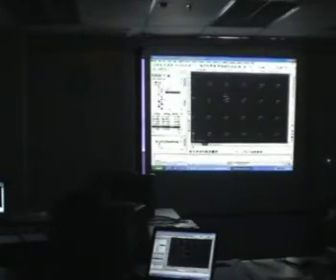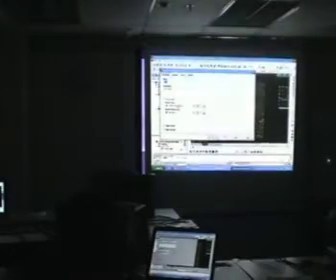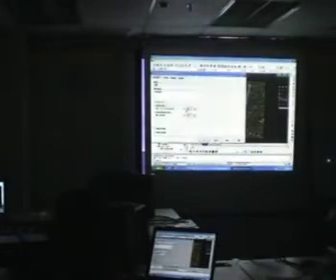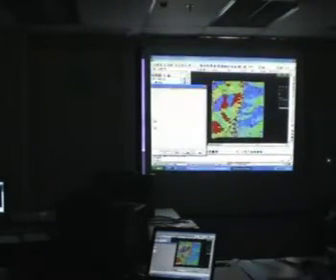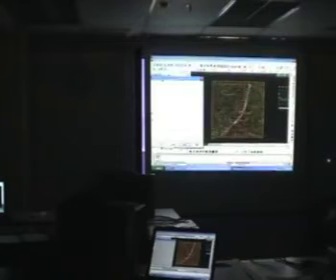Maybe I'll show you the difference between all this. I'm just going to zoom out. I go to the surface, right click, go to Properties. And this is the surface style, meaning how we're representing the surface at the moment. Right now we're using contours and background, so it's barely visible because it's all grey. Let's say I switch. I want to see borders and triangles and directions, and I click apply. You can see how it's updated automatically in the background. Now these are all the triangles, colors. If we want to see another one, say I try slope arrows, apply. Now see the contour lines have changed color and there are slope arrows.